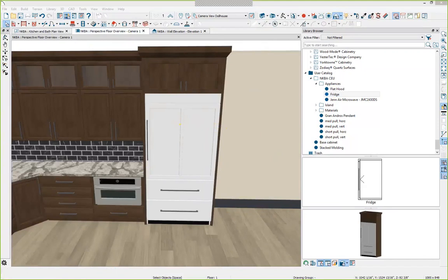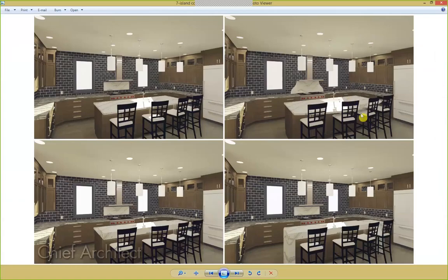So next, we are going to add an island into the plan. And then we're going to show how the software can be used to quickly create various island design options for your client. We have 4 options here. The first has a basic 9-inch overhang. The second option is going to curve that overhang. You can then make that a 6-inch block if you wanted to.